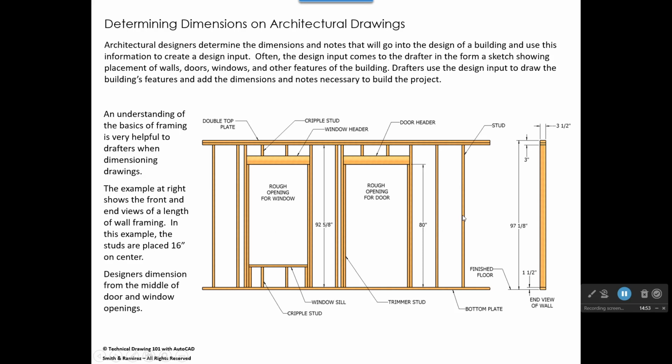then every 16 inches there should be a stud depending on if it's 2x4 framing, they'll probably go 16 inches. If it's 2x6 framing, they could probably even go to 24 inches because they've got more structural strength in a 2x6 versus a 2x4.